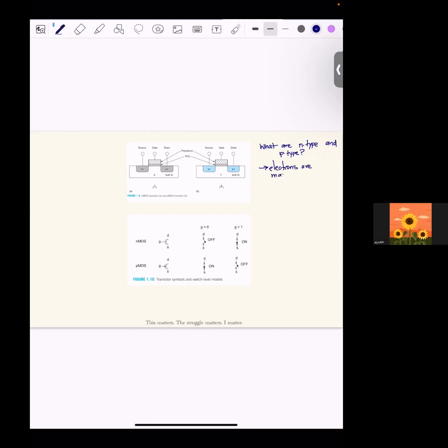Because N-type stands for negative, and electrons are negative. They are the majority carrier. So then what is the minority carrier? P, positive holes. I'm also going to draw a diagram of what it looks like in the textbook so that you see the movement of the electrons. So see, it jumps out of the hole, it leaves a hole.